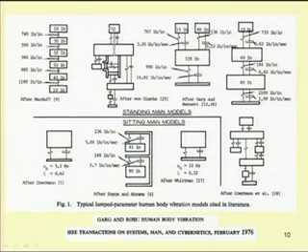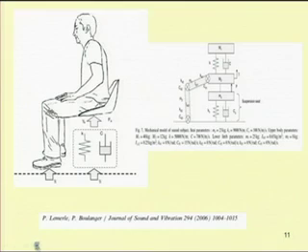One can have a 2 degree of freedom system also, or a multi degree of freedom system. This is the sitting position. The leg is modeled as 2 links, then different postures and the sitting arrangement are modeled by a spring mass damper system, and the backbone and head are also modeled by different spring mass damper systems. In this way one can model different systems by different lumped parameter models.